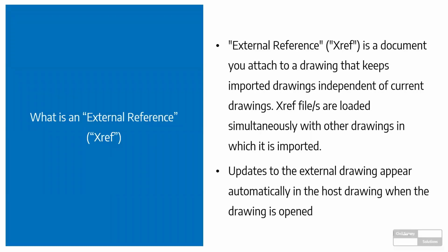When you insert a drawing into AutoCAD or into a CAD file, that inserted block is a static block, and if it was to change, you'd have to manually change it in the drawing, or you'd have to redefine the block in your drawing by bringing in an external file once more. Whereas with an Xref, we can actually reference those external files, and any files that are modified, that are attached to your current drawing, will update in your current drawing.